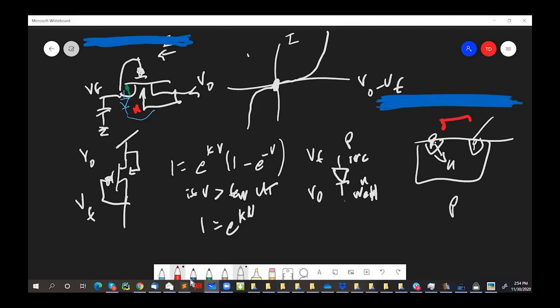Here you have your gate. And normally, if you make a switch out of an NFET, suppose we put an NFET switch here instead of a PFET, even if you cover it with metal, if there's an opening in the metal somewhere nearby, then this NFET acts like a photodiode. And it's very difficult to keep it from soaking up electrons and leaking.